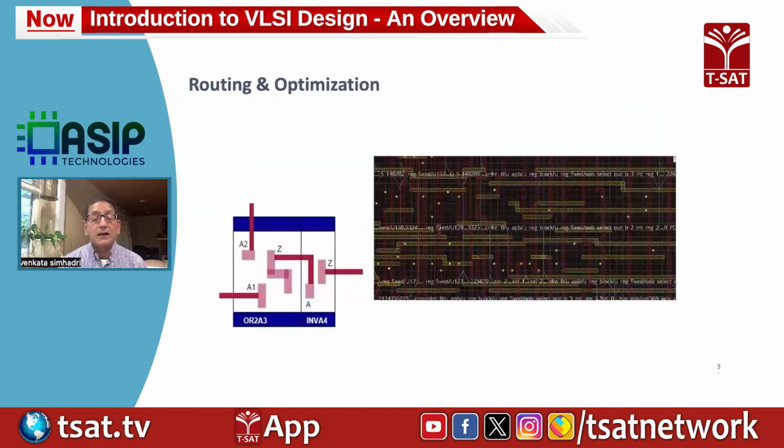So once you have the placement and clock tree in place, then you have to start connecting these signals with the actual metals. And the current day, let's say if you're designing a chip for a TSMC 5 nanometer process, you may be using more than 10 layers of metal stacks to connect these gates. And it's all done automatically with the place and route tools.